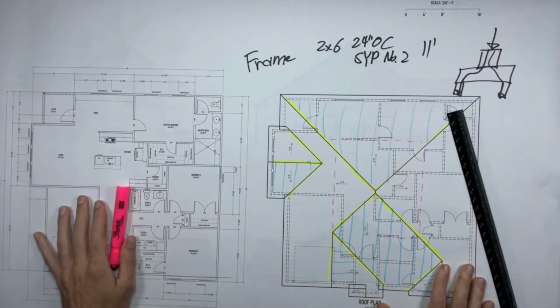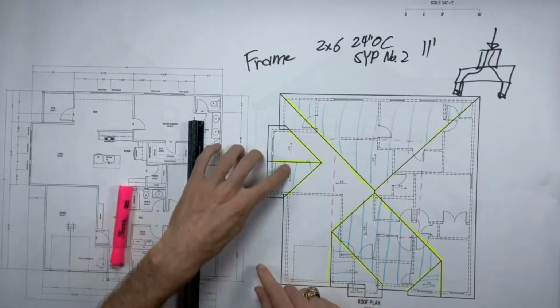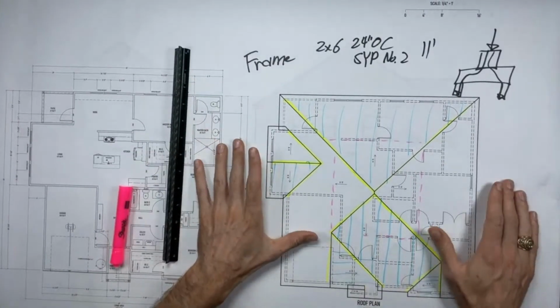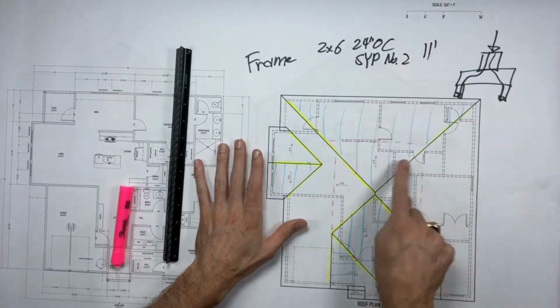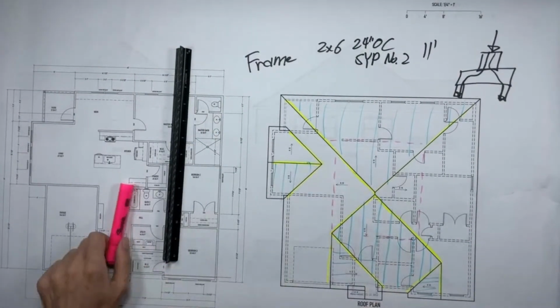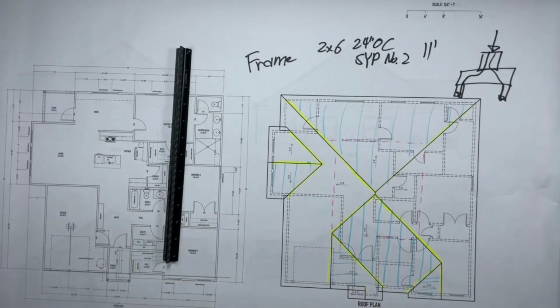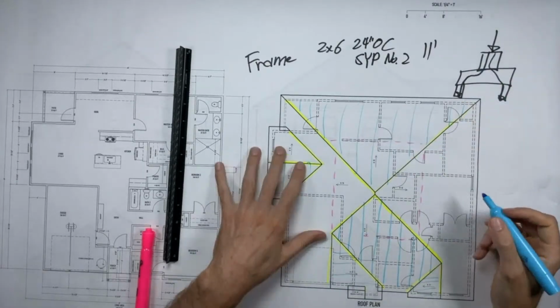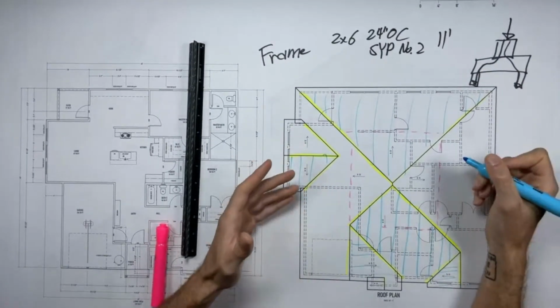So this is obviously shorter than 11 feet for these rafters. So I know my rafters are good. If I do this and I put these bracing lines in, I'm good. I've got 2x6s, 24 inches on center. Structurally, I'm sound. So I put the purlins in, but I didn't do anything to hold the purlins up. Right now it's just a little stick running hot dog ways, running lengthwise down the framing. So let's add some braces.